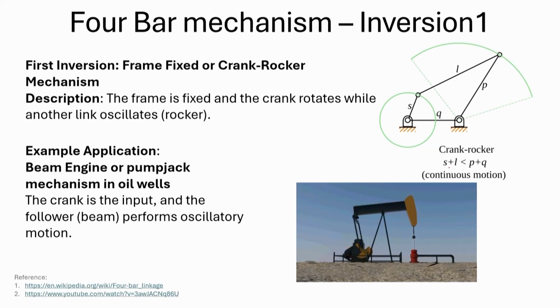There is a particular condition of course there, that is S and L, the length of them together has to be less than P plus Q for continuous movement. This is something that you have to satisfy. So, this is something that we will see in the pump jack mechanism in oil wells. The crank is the input and the follower performs the oscillatory motion.